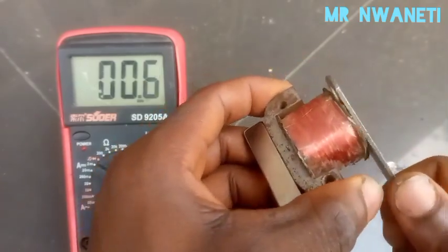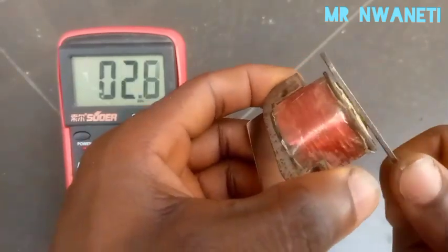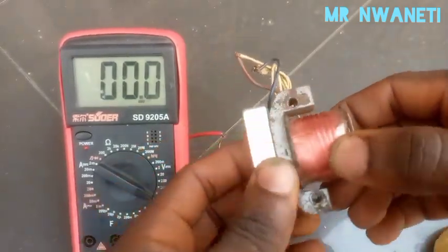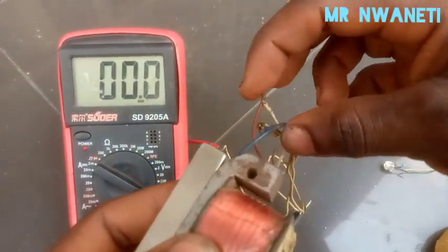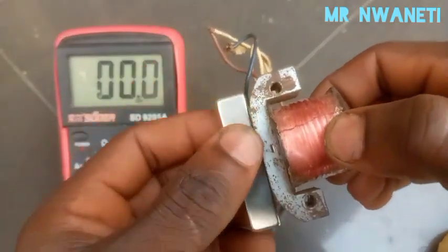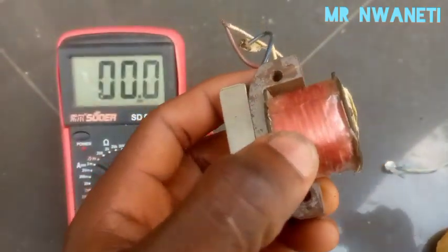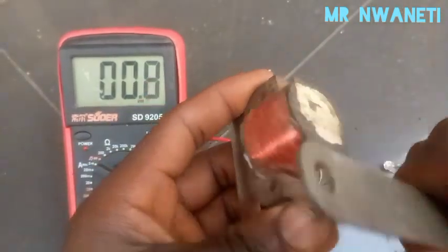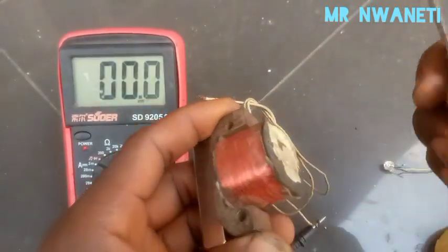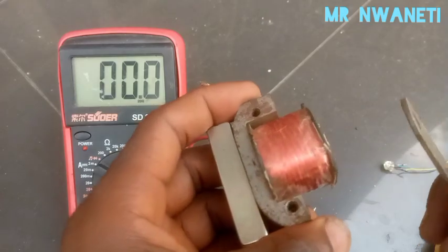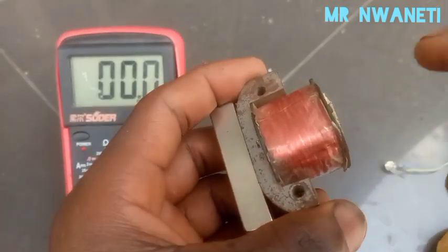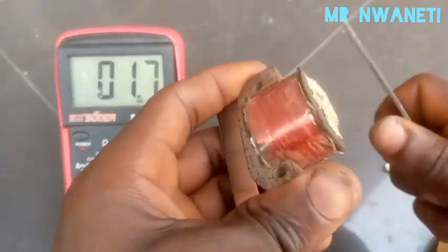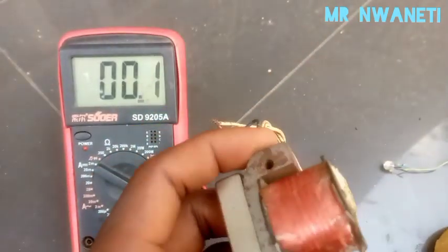You can see. From what I experimented with this design, even when you shorten the coil and load the generator, it won't have a direct break, because only the iron is moving toward this coil. It is not a permanent magnet or an electromagnet. So only this iron is moving here. You're just cutting the flux, and there will be an induced voltage.